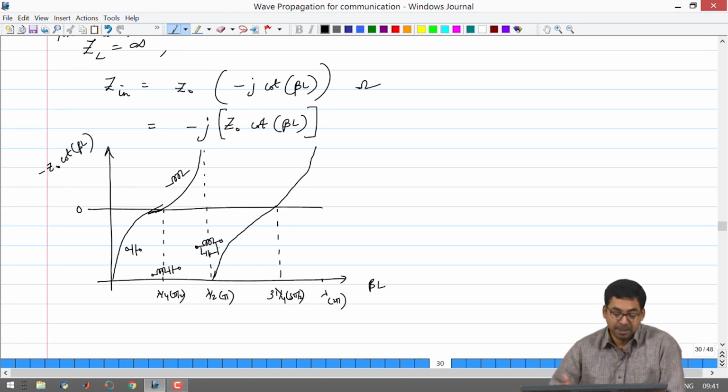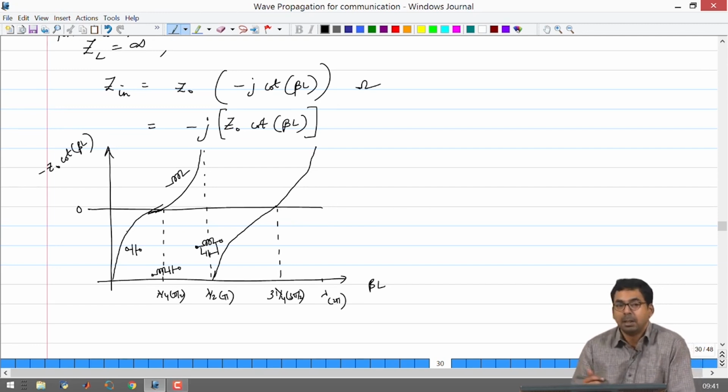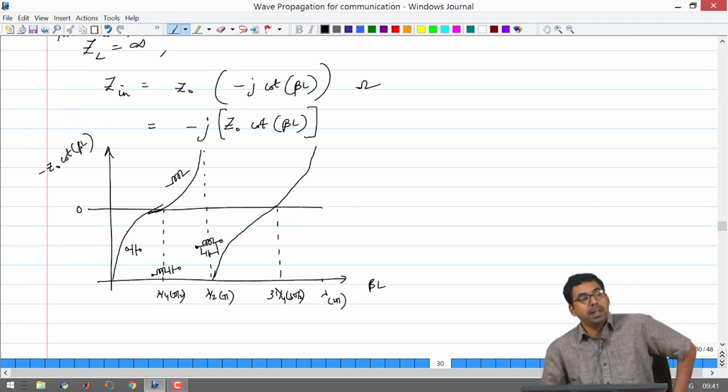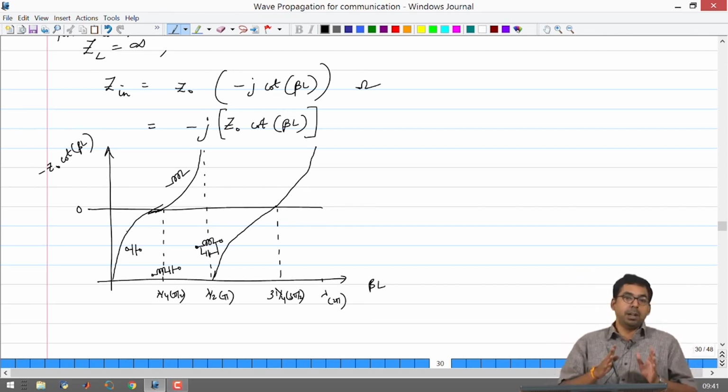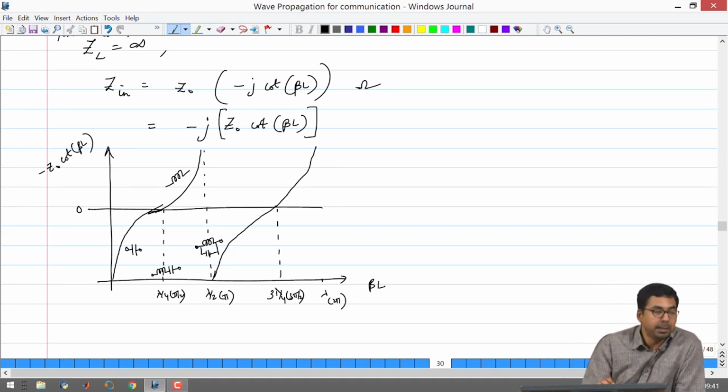So, that means the technology for making any of the passive circuit in high frequencies is the same. You need to know how to make transmission line, that is it. The remaining job is where to cut the transmission line so that you can make any of these passive components. When we began this course, we began by saying that the equivalent circuit of the transmission line is going to be some chopped up versions of L and C arranged together, alright. But it is also true that if you were to replace a transmission line with a lumped element, this is how one could do it, alright.